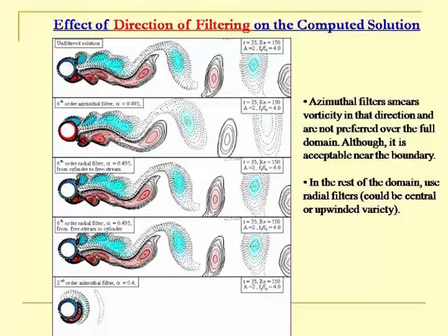However, if you now apply a filter in the theta direction, it kind of performs a mixing operation in the theta direction, right, and that numerical mixing actually prevents separation, and that is what you have seen here, that you would not have to worry about numerical separation at all. The results are wrong, that is a different issue.